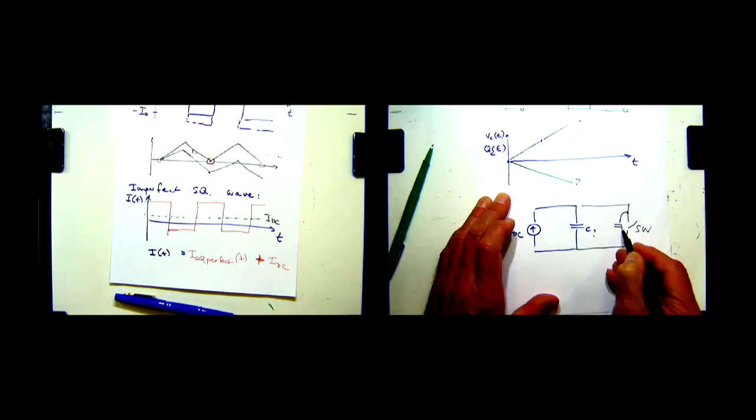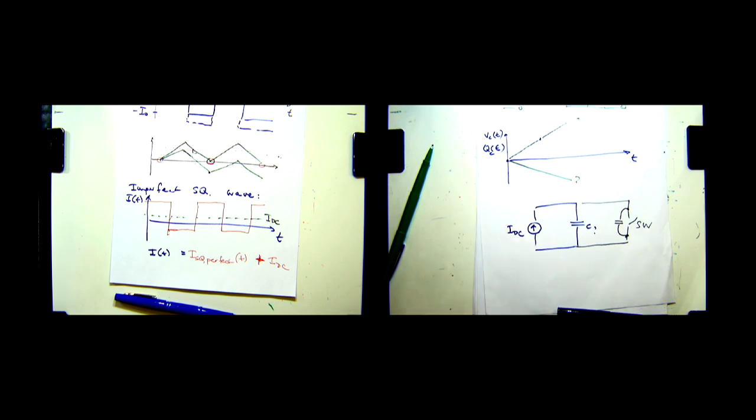The designers chose another solution, and there are good reasons why. This switch would add a lot of capacitance. Any switch you can buy is the switch plus a big capacitor like that. That wouldn't be good, because it basically masks our touch capacitance. Unless you have really big hands and fingers, we won't be able to detect any touch. With the right technology and so on, we could do that. The other thing is you need a clock for that switch. So, are there other ways to do this? Simpler ways, actually.